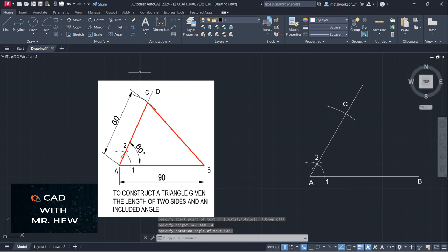All right, the next step is to also draw a line from B to C. Turn on object snap. Enter. All right, now what I have to do with this line, I'm going to break the line, this line, let me call it D for you.